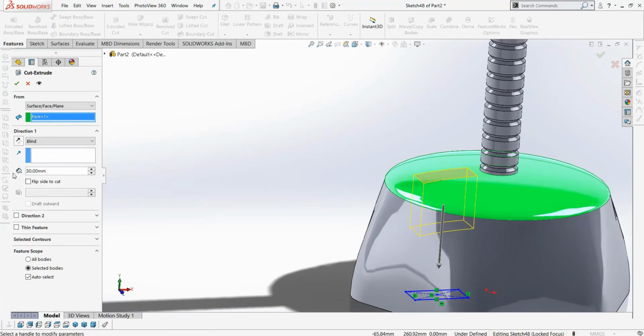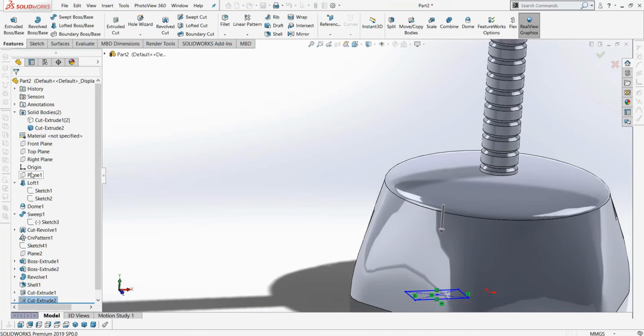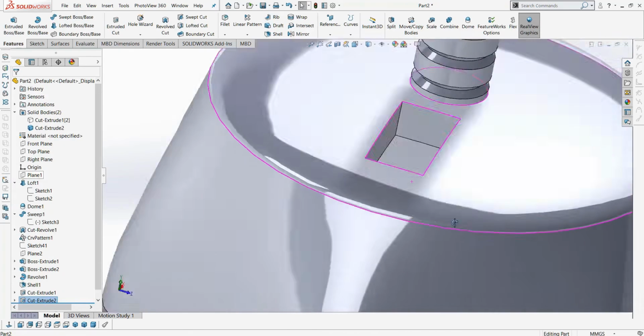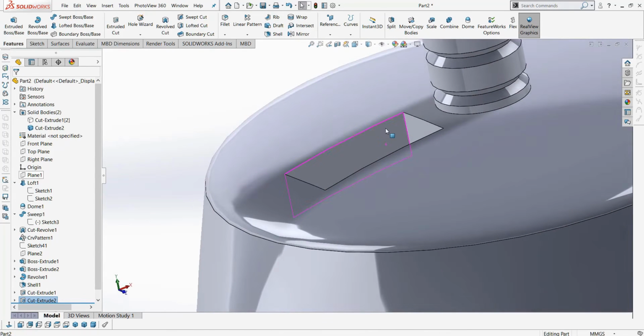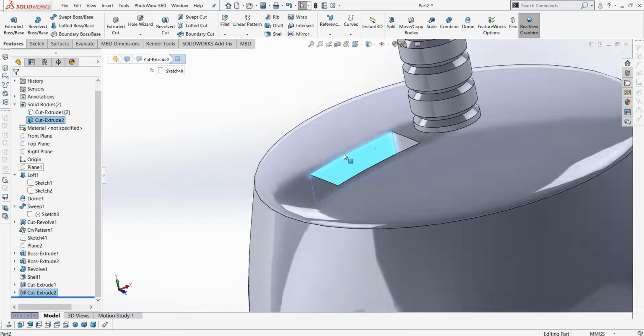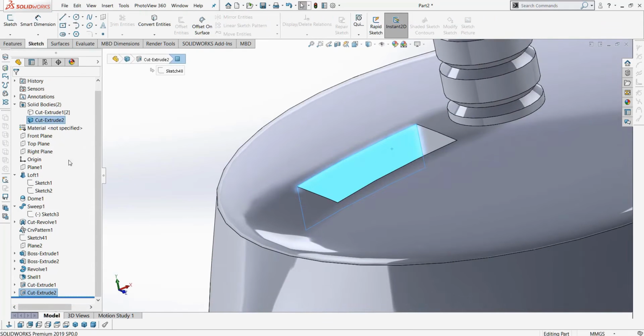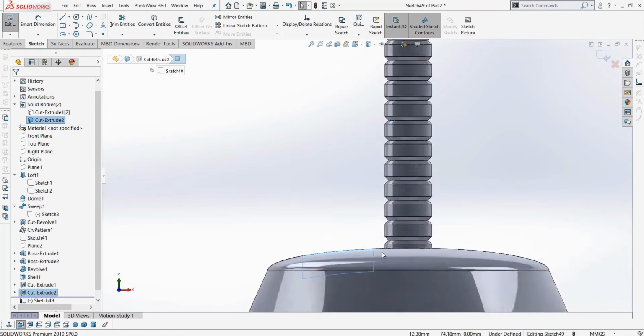It's better to work with a number. For example, start with a size of 10 and reduce it by 10 millimeters for me, so that a space is created here. Now, I will select this face and say that I want to draw a sketch.